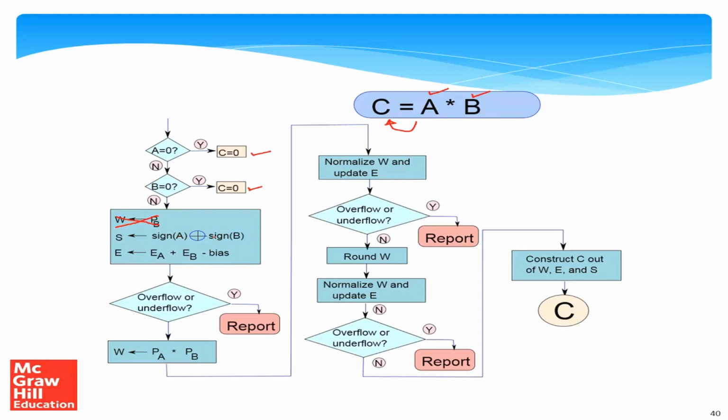So basically the way that we are representing the sign of A or B is by the sign bit. If the sign bit is 0, it means that the number is greater than or equal to 0. If the sign bit is 1, it means that the number is less than 0. As you can see, if both the numbers have the same sign, their exclusive OR is 0, so the number is positive. If they have different signs, the exclusive OR is 1 and the number is negative. So the sign bit is 1.